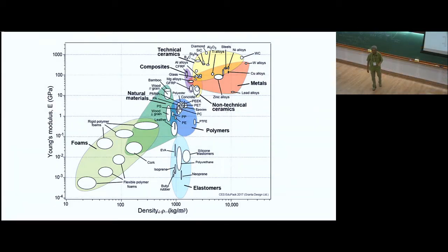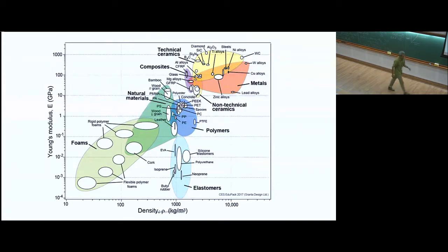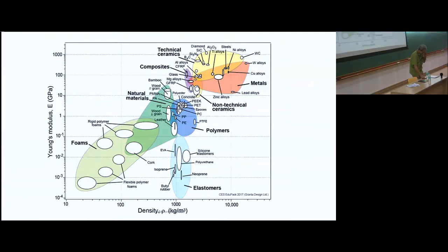10 to the power 4-ish pascals. Is that right? So what are you taking? You're taking a 100 kilogram person and 10 meters per second squared, so there's 1,000 newtons. And I'd say this is less than a meter squared. So I'd say probably the number's larger, but not a whole lot larger. But you can see that these are perfectly good things to stand on. This is getting not so great to stand on. Those are the materials you use when you want to absorb impact, for example.